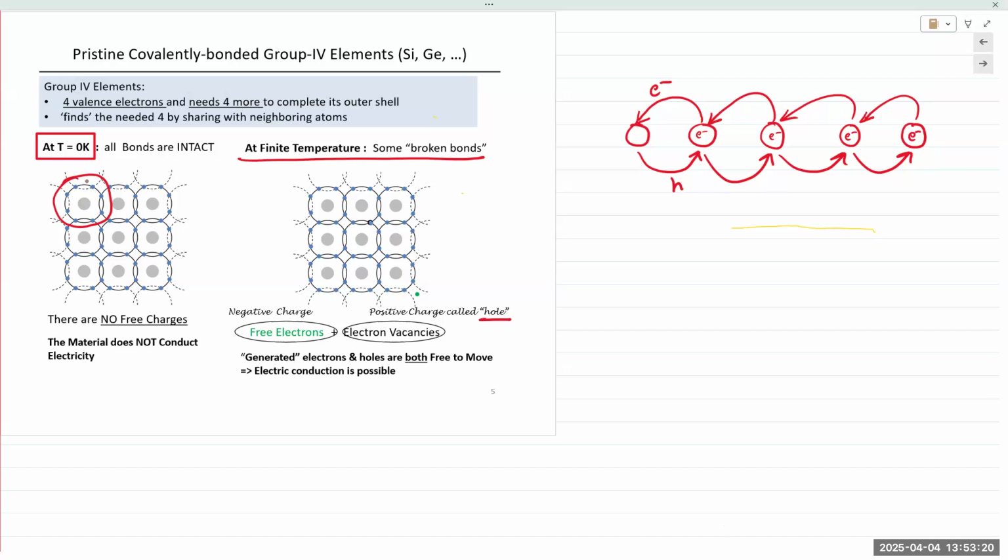The reason it is said to have positive charge is that when an electron moves out of a spot, the positive charge is bound in the nucleus. So the hole is bound to that nucleus. It is said to have positive charge. And so in semiconductor theory, we analyze with two subatomic particles: electrons, which have negative charge, and holes, which are said to have positive charge.